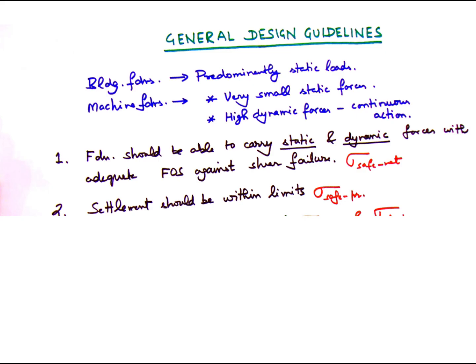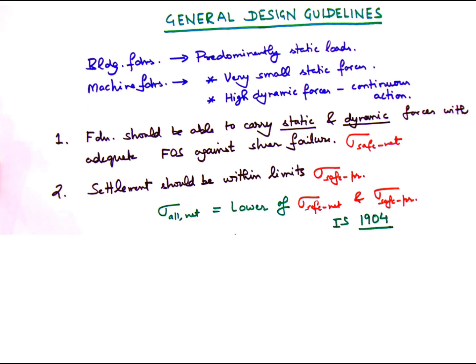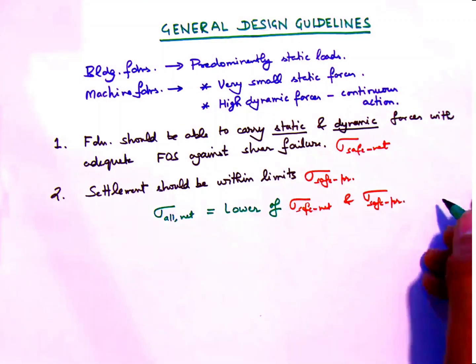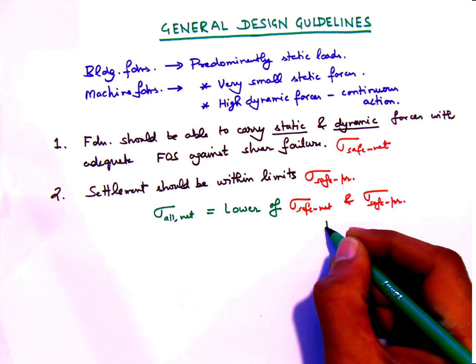Essentially, the allowable net bearing pressure is supposed to be the lower of the safe net bearing capacity and the safe bearing pressure. These pressures are to be specified in the geotechnical investigation report. The geotechnical engineer does the investigations and the calculations as per IS 1904.